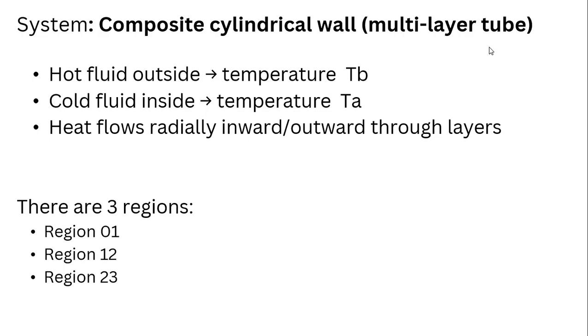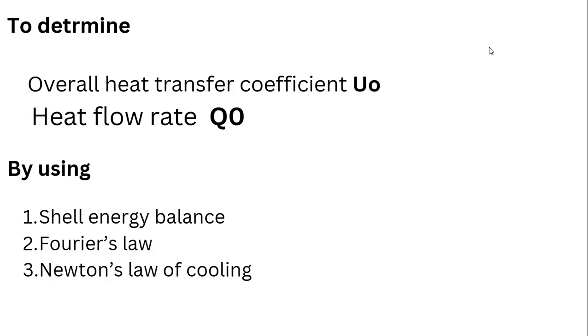Heat flows radially outward through the layers, and as we discussed, there are two regions. The derivation uses three fundamental laws: shell energy balance, Fourier's law and Newton's law.